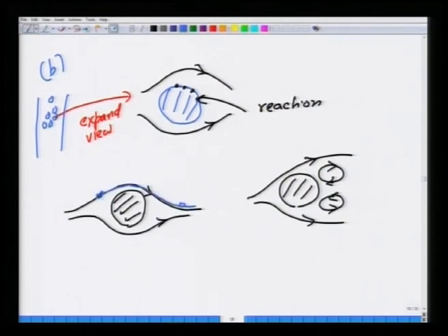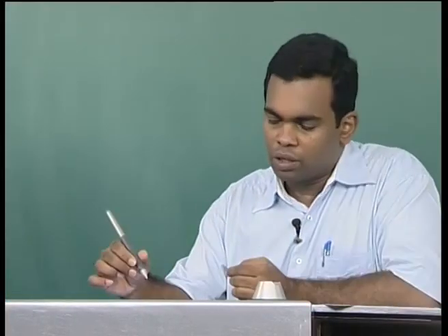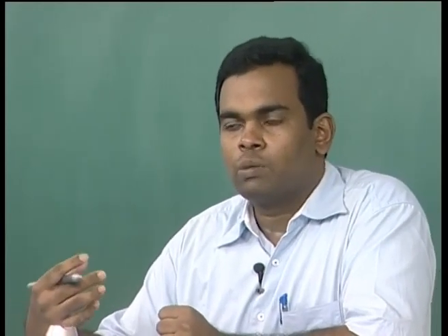There is no mixing along the streamline, whereas here there is a lot of mixing. So, the details of the flow pattern around each particle have a critical implication on the rate at which mass transfer happens, and this is not just true for this example. In any separation process, where you have two streams, one dispersed in another, it is important to have a detailed understanding of the micro scale flow about each particle or each phase.